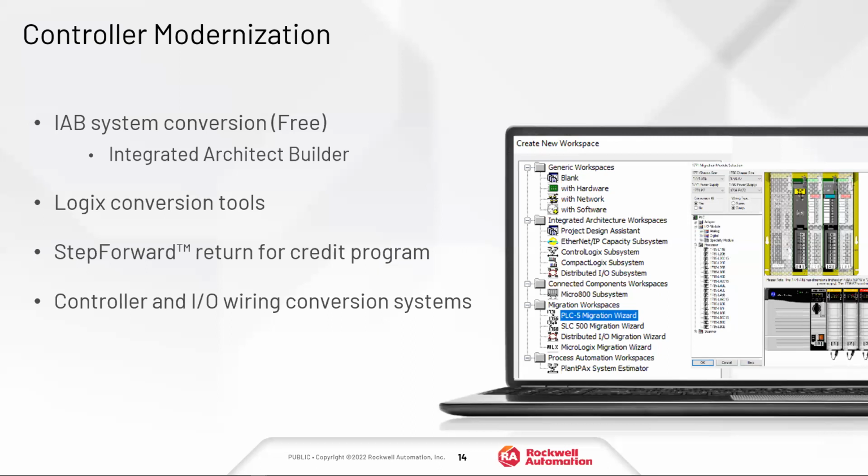So that's kind of step 2. Step 2 when you're owning a controller modernization is to utilize those conversion tools. And they're not 100% conversion. It depends on the complexity and some of the instructions that you use in your older project. But typically, you'll convert 80 to 90% of your logic from the old stuff to the new stuff. So that's definitely something you want to utilize in a controller modernization.